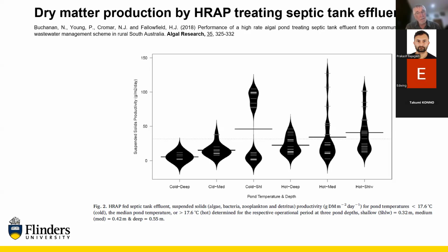It's probably not going to be, in my view, something you do on a commercial scale. You'd need very large areas to produce significant quantities of biogas, but it's good to demonstrate that you can do those things. You could equally do static anaerobic digestion of biosolids and produce methane to generate electricity to run your high rate pond. You could do that.